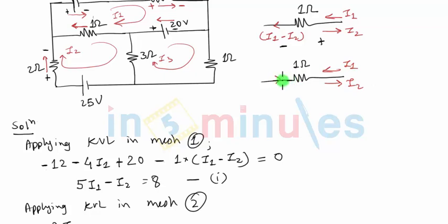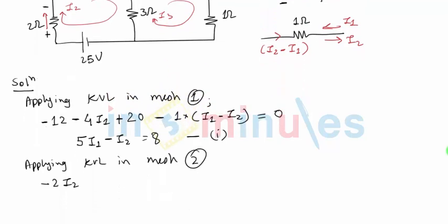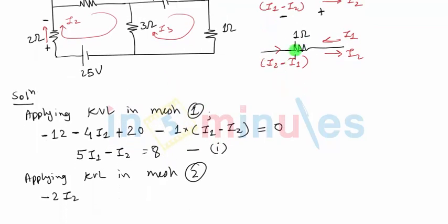Now the current which is flowing towards right will have the same direction as I2, and hence this time the equivalent current we will call I2 minus I1. So what will be the new voltage drop across 1 ohm? Current flowing towards right will give us the drop as plus minus, so a fall in voltage again. It will be minus 1 into I2 minus I1.